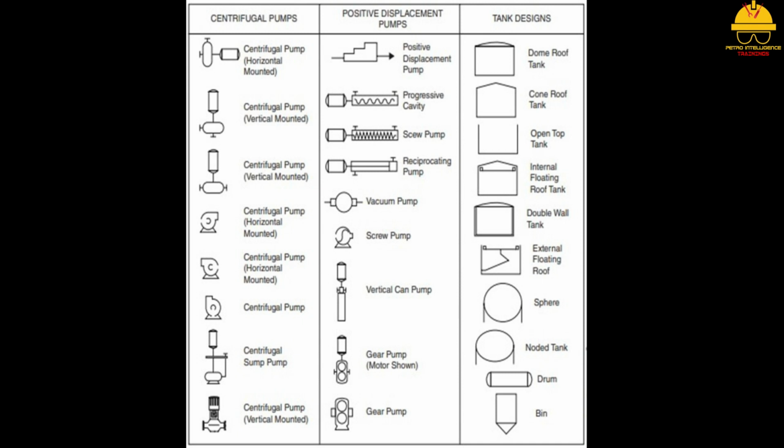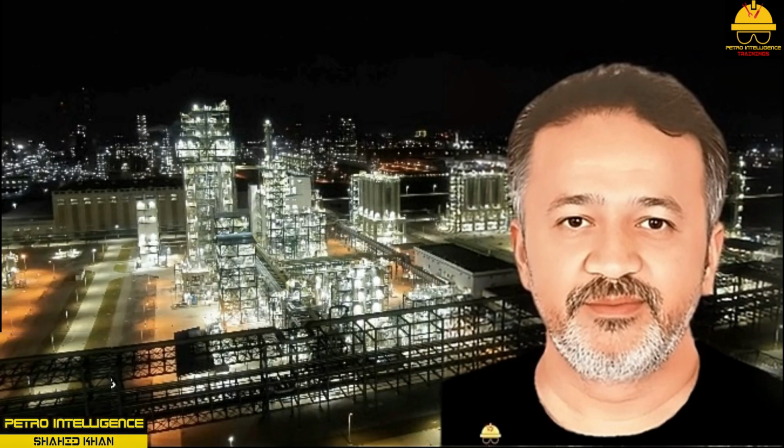Reciprocating pumps typically include piston, plunger, and diaphragm. These operate with a back-and-forth motion, displacing a predetermined amount of liquid. Rotary pumps use a rotary motion that displaces a specific amount of fluid on each rotation. Rotary pumps include the following designs: lobe, gear, vane, and screw. A pump and tank system includes piping, valves, instruments, and control loops as well as the pump and tank. These systems are designed to be circulated.